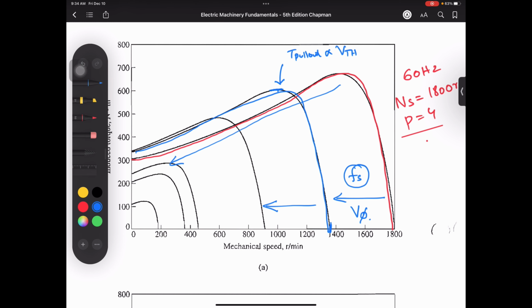So what I mean is, if you are designing a plant and you require this much torque, you are going to select a machine so that it can even run at approximately 180 RPM and it can still give you that required torque. So you will not pick a machine which has a curve like this, where you say, yes, I have taken it up to here, or maybe your requirement was something here, so you got a machine according to this point. But the same torque will not be possible in the lower frequency range.